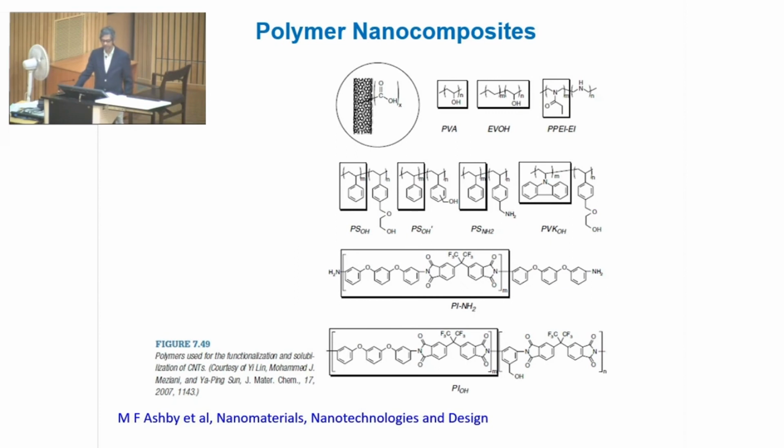So that is the main mechanism. Other than that, you have chemical bonding or van der Waals interaction between the CNT and the matrix. In addition, it is believed that the key factor in forming a strong bond between the polymer matrix and the CNT lies in polymer morphology, especially the ability to form large diameter helices around these individual CNTs. Strength of the interface is then due to molecular level entanglements of the CNTs in the matrix.